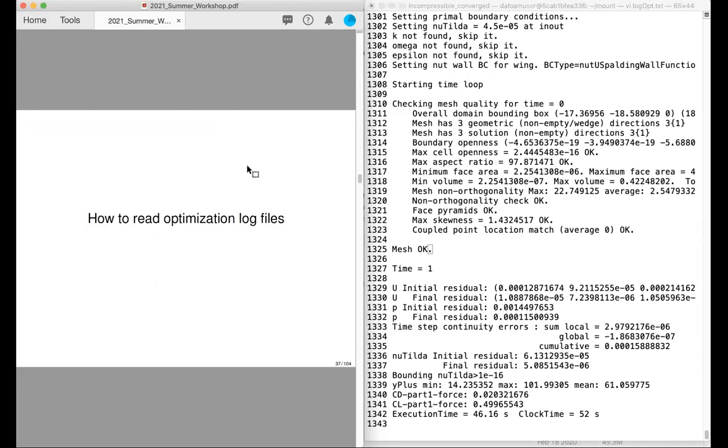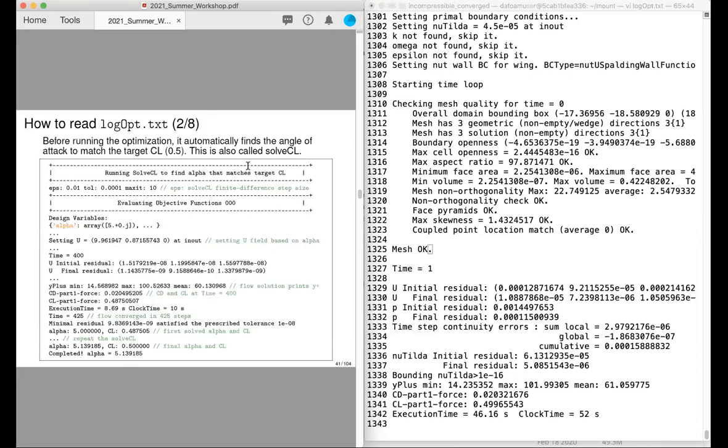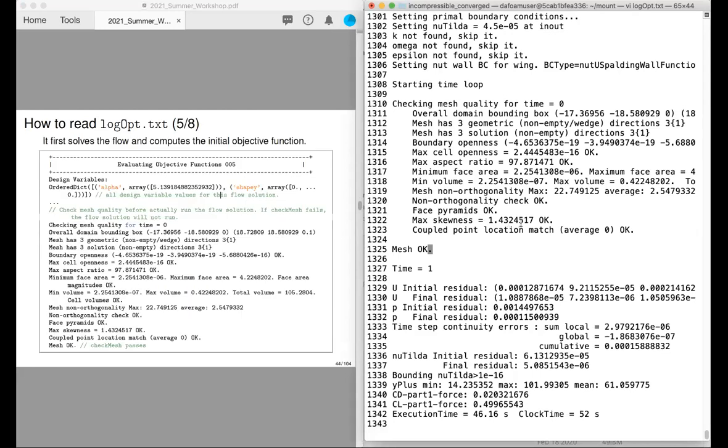But it does have a mechanism to take care of this failed mesh quality. Because I have experience working with OpenFOAM itself, not with DAFoam, that in some cases when the meshes become really complex, like not airfoils, but very weird internal flow channels or so, you might eventually want to accept some failed mesh checks because you cannot get rid of them, particularly if you use snappyHexMesh.